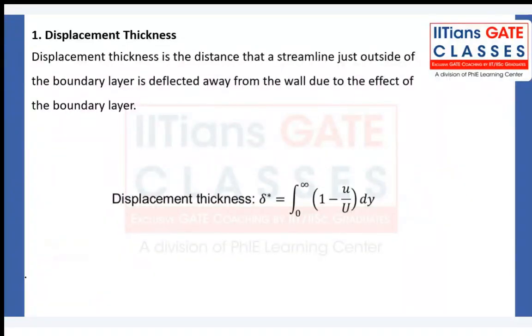Wall is a fixed wall, right? So that also is transported to the second fluid layer, and above that we have the higher velocity fluid layer that is also being impacted because of the property called viscosity. That is a flow property, and because of that eddy viscosity is generated because of the momentum exchange in the turbulent flow. In laminar, it doesn't happen. Laminar flow, they are flowing in a parallel manner, but in a turbulent flow you will see after a certain point of time a lot of intermixing.